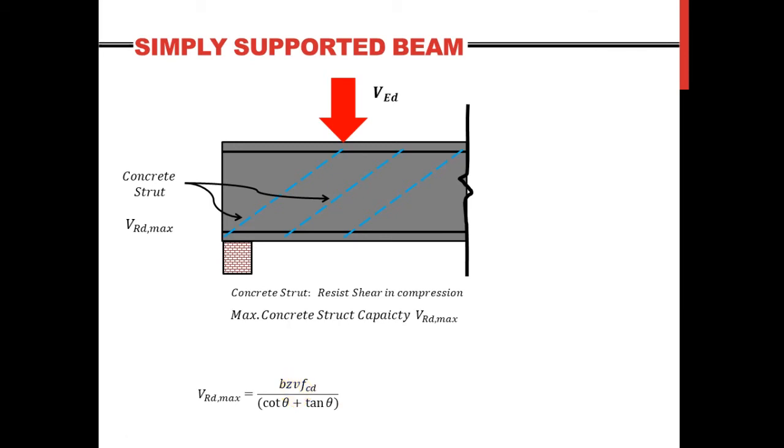We'll see what that is equal to later on when we solve for our example. Now there is the theta again, and to put it in simple words, theta is related to the applied shear force, the VEd. The bigger the VEd, the bigger the theta gets, and the less the VEd, the less theta gets.